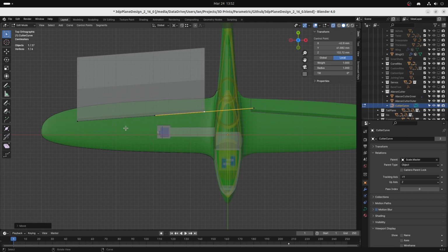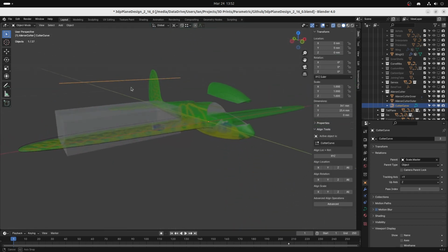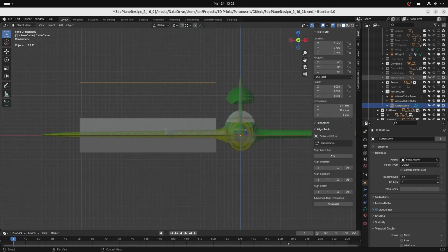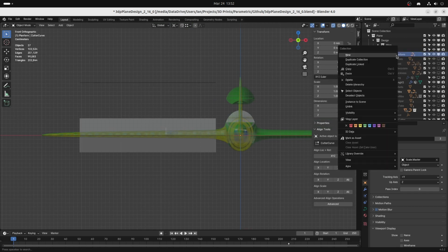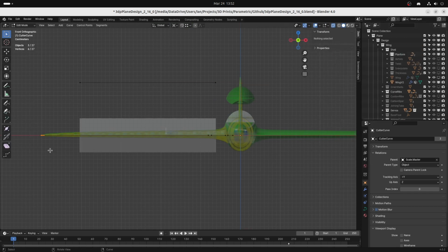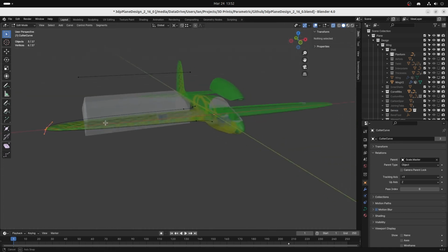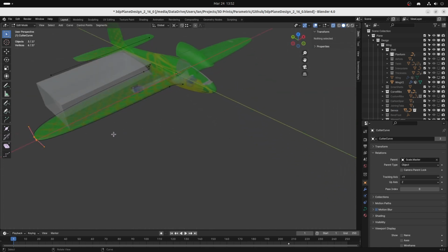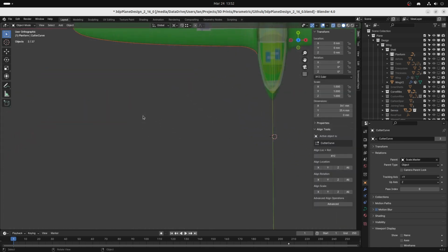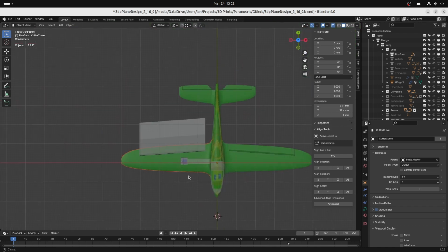By default, the vertical positions of the corners are set by the height of the leading edge curve. This isn't really a perfect solution, as the twist of the wing and the shape of the airfoil can make the trailing edge a bit higher or lower, but generally it gets quite close, and then there are fine adjustments available. For the cutter objects themselves, there are parameters in the Modifier tab.